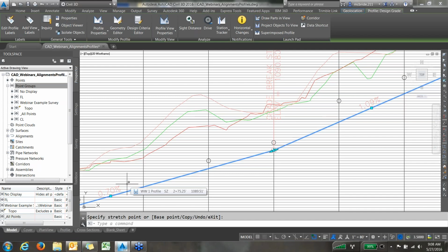You got to go back to Engineering Field Tools, plug in these new grades, and see if it changed the depth of your waterway significantly. So it's kind of going back and forth, sort of a several step method of iteration. Hopefully you only have to do this once or twice, and it's not too hard. Luckily, with Engineering Field Tools, you just plug in the numbers and it gives you the new depth. So this makes it fairly simple.